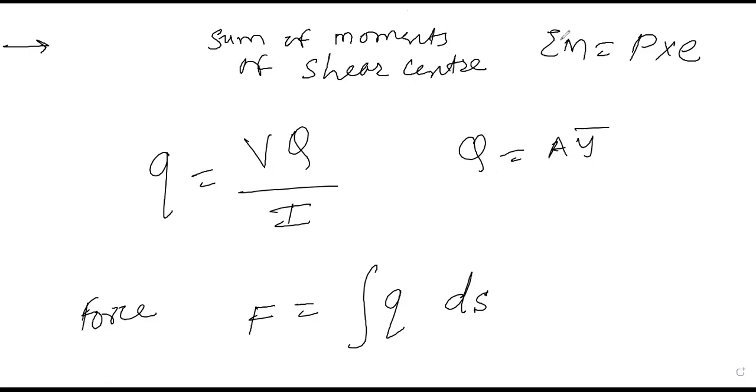Summation M is equal to P into E, right? Where P is nothing but the force which is applied. So from that we will find out the value of E. So these are the equations that we have to use while finding out the shear center.